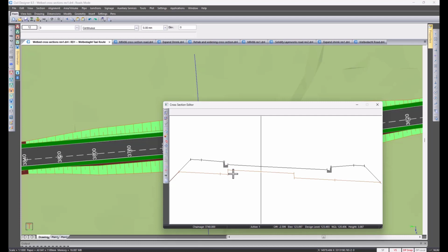Okay, so we've looked at the section editing, the road section editing menu today, which ideally would allow you to tweak your cross sections like we did with those berms, just to get to a final design that you're happy with, and then also to get your calculations, your volume, mass or volume calculation to what it should be.